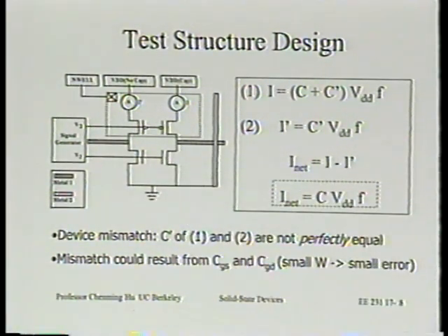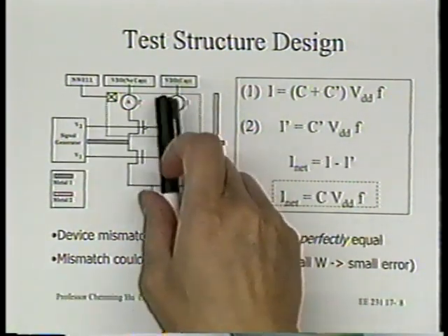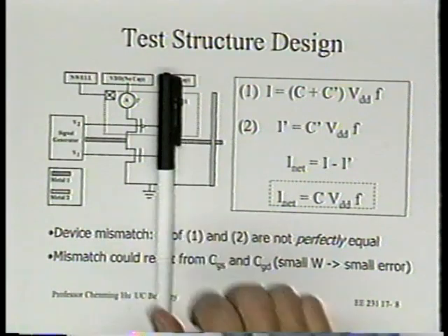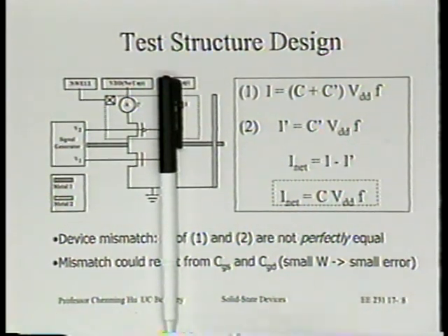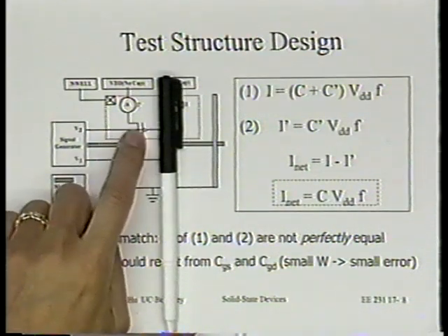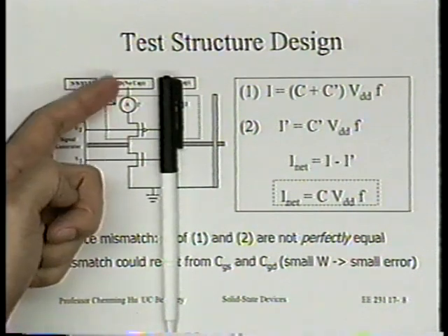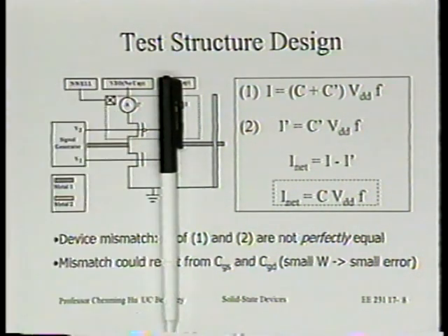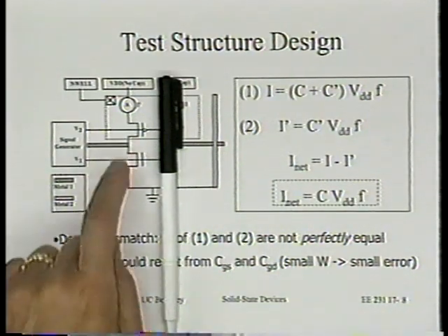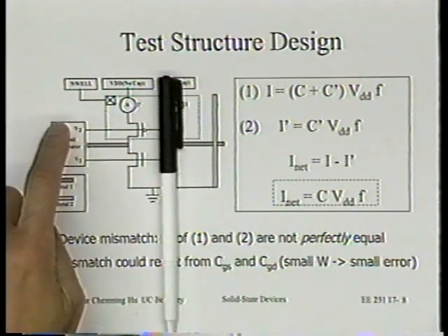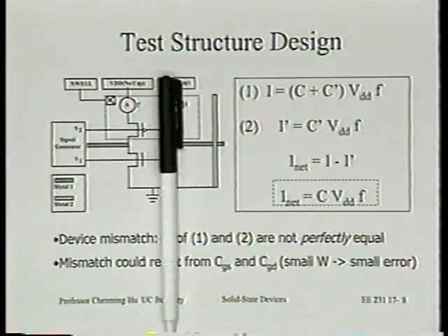Let's just look at one side right now, just the left-hand side. What looks like to you is an inverter, isn't it? A P MOSFET on top, the circle indicating the P MOSFET, and an N MOSFET on the bottom. Connected between VDD and ground, with this ammeter in between. So this is an inverter, except for one difference. These two gates are not driven by the same clock. The two gates are driven by two different clocks, V1 and V2.